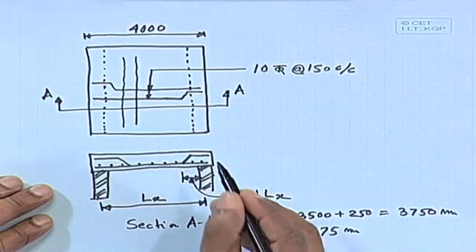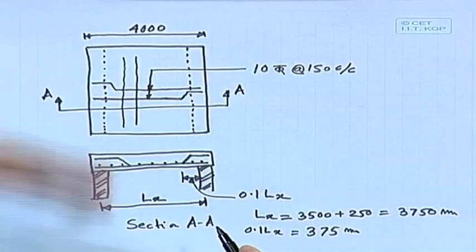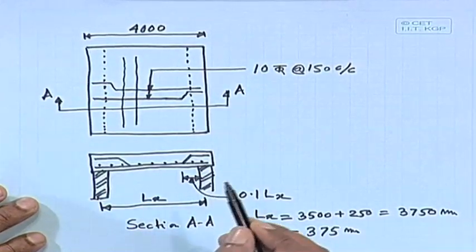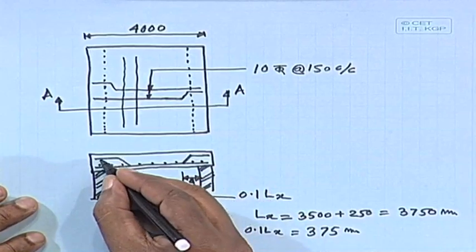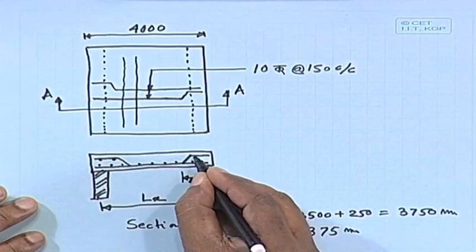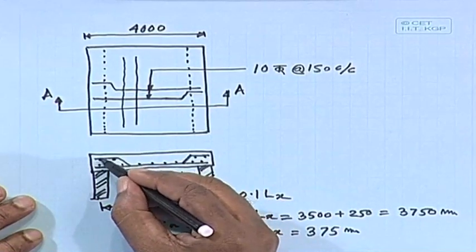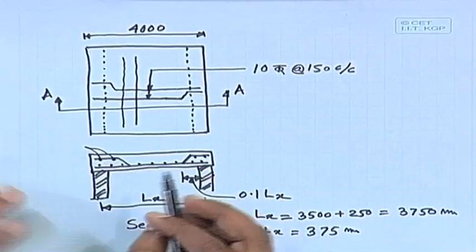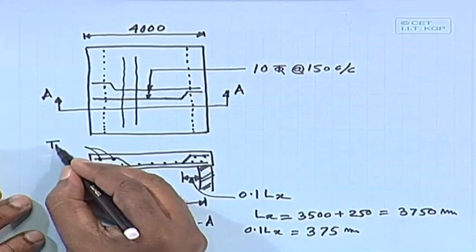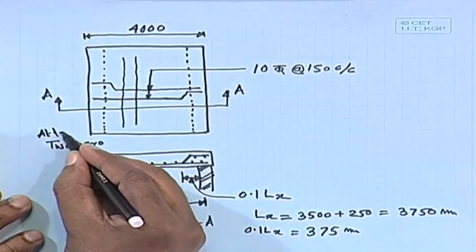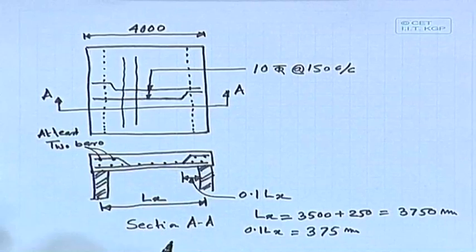We shall get it like that, because all the longitudinal bars are cut in the other direction. So, we will get all the circular ones with respect to the bar diameter, and similarly at the top also. Please note, we have to provide at least 2 distribution steel bars at the top to hold it. Even if the slab is small, you have to provide at least 2 bars.